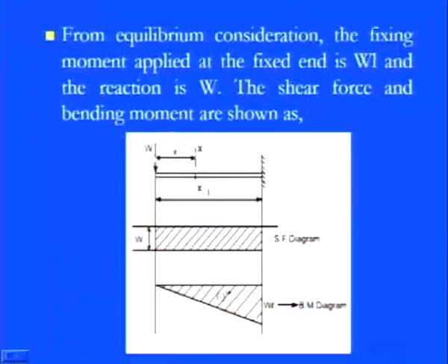So you see here it's pretty simple. From this cantilever beam, if we have a W which is a single loading condition, then the contribution in the shear force as well as the bending moment is from only that load. This is the applied load, and the shearing load comes from the reaction part. From these two parts we have a simple shear force diagram, a rectangular part, and the bending moment diagram is the triangular part. The maximum value of the shear force is minus W, the maximum value of the bending moment is minus W into L, and the minimum value of the bending moment is 0. So like that, we can easily calculate all those things for a cantilever.